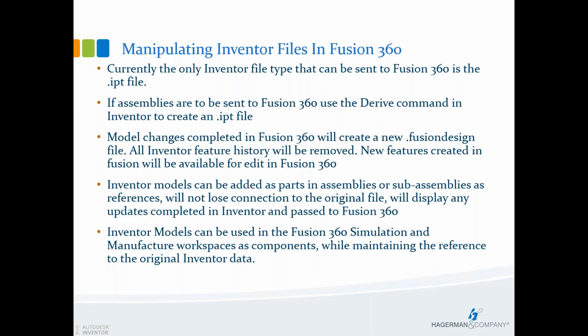If you have assemblies that you want to send to Fusion, one method would be to turn those into an IPT file using the derive command in Inventor. There's also tools inside of Fusion that allow us to upload IAM files and their corresponding IPT files.